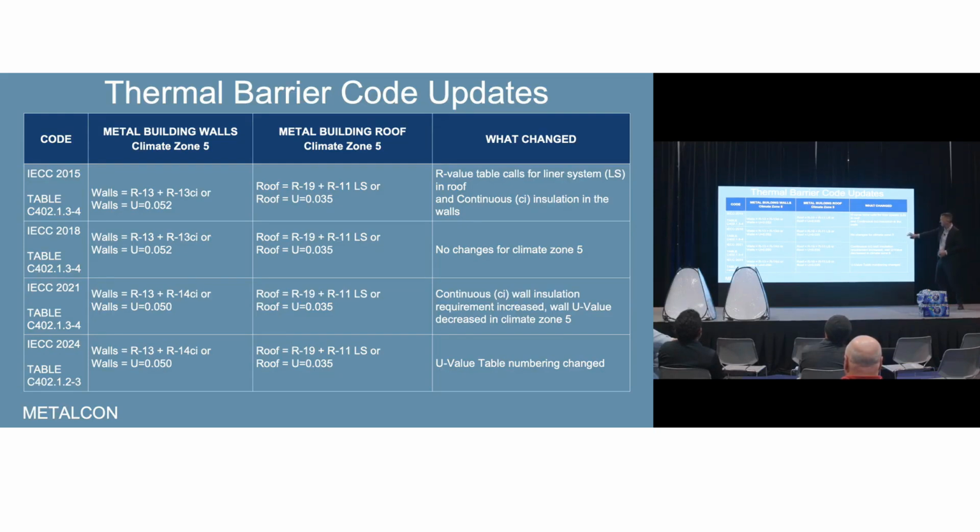They've realized that they've given us systems that is a whole lot of insulation. To make this work in the roof, we're typically at 12 inches of fiberglass. To make it work in the wall, we're over here at about 9 inches of fiberglass. So they've said that's about what we can physically put in with those systems. So let's go a different way. Let's require air barriers, let's require vapor barriers, and let's make the envelope tighter.